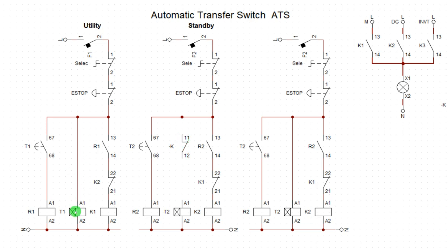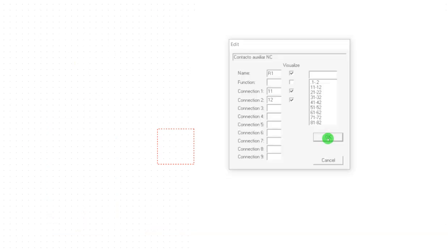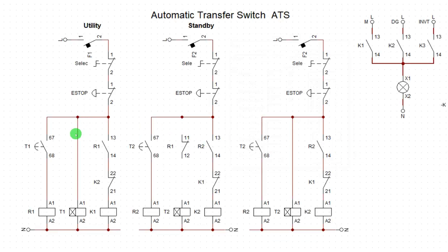It's coming from here. This is arrow 1 belonging to mains. So I will put arrow 1 contact here because it's my priority line. It is the one that is going to give permission for this. So when this one becomes active, here will open. Once here opens, this power will go off. This one takes over. So I'm going to do that here again. I'm going to put another contact again.